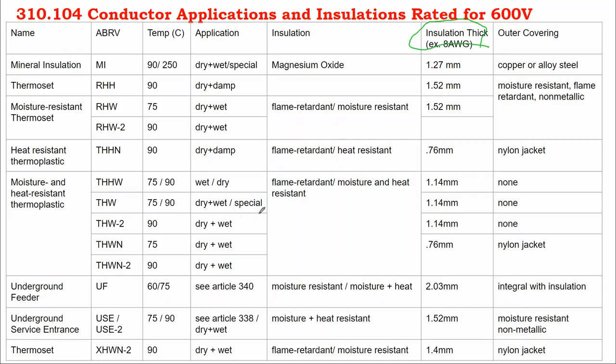So it follows that wet rated cable is a little bit thicker than dry rated cable. If you have an indoor cable, it might have a thinner cable jacket. You replace it with an outdoor cable, then that outdoor cable might not be able to fit so well into the conduit.